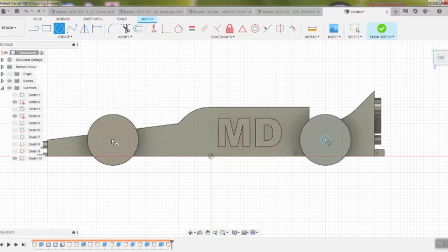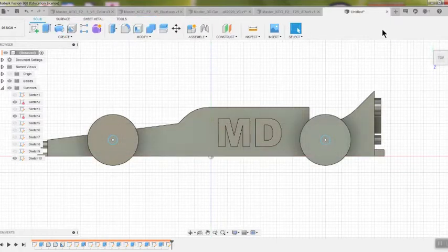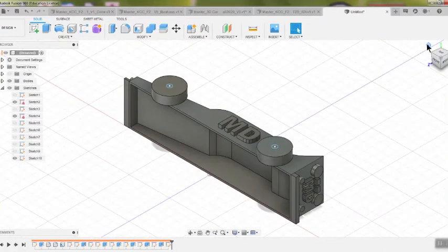Come to the center of the wheel. Left click and release. Let's make sure we hover over and snap 2.828. Keep it steady. Left click and release. And there you go. Okay, let's finish this sketch by left clicking and releasing Finish Sketch.